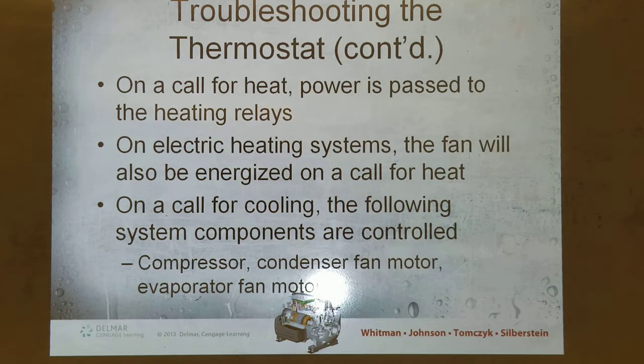Troubleshooting the thermostat, continued. On a call for heat, power is passed to the heating relays. On electric heating systems, the fan will also be energized on a call for heat. On a call for cooling, the following system components are controlled: compressor, condenser fan motor, evaporator fan motor.